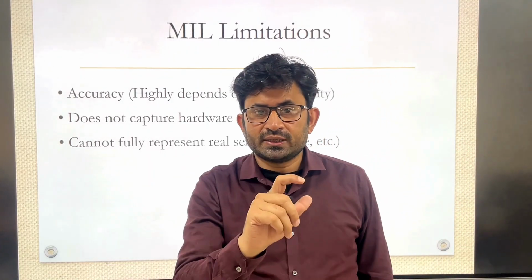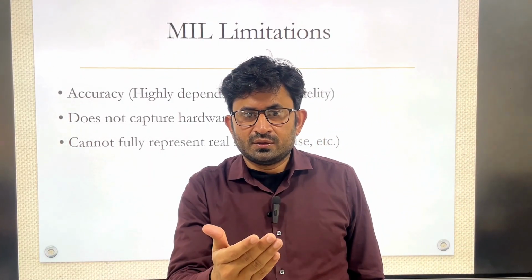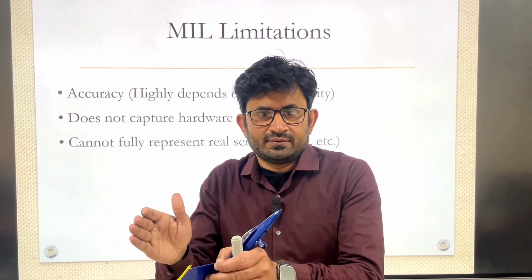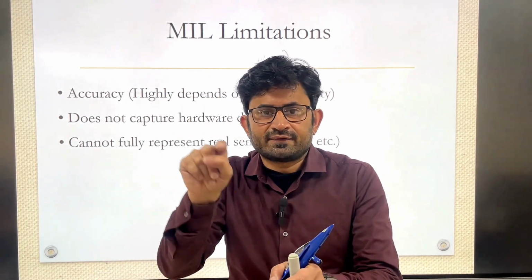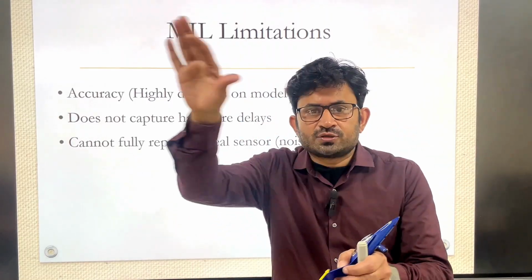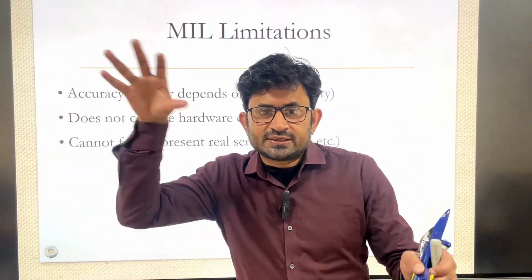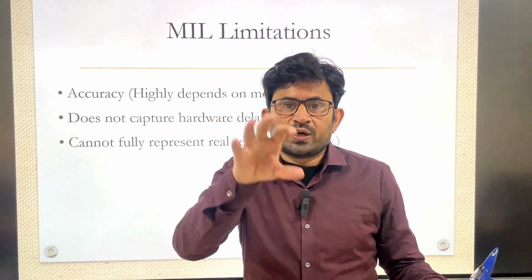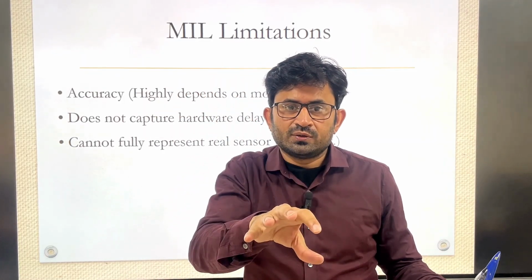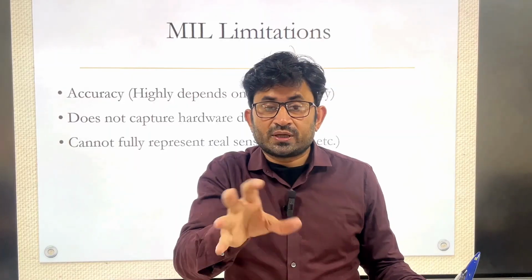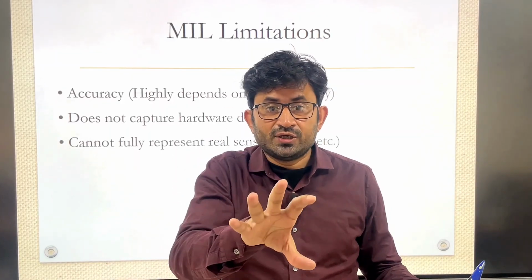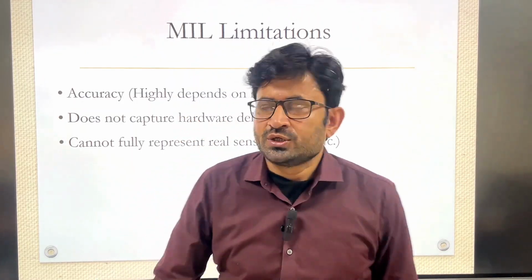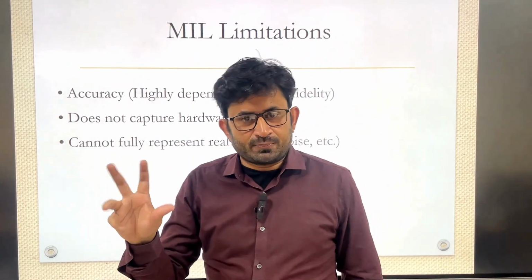Because whatever you are modeling, like the aircraft model, that is not 100% correct. And the controller gain, because you are analyzing the aircraft and designing the controller based on this response only, and this response is coming from the aerodynamic model and propulsion model you have designed. So if this is inaccurate, the controller which you have designed will also have inaccuracy. So that means accuracy is a problem in MIL.